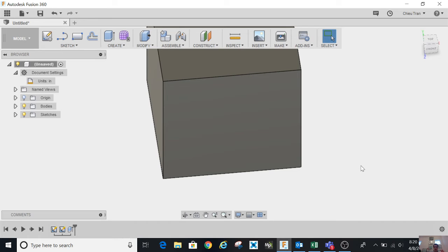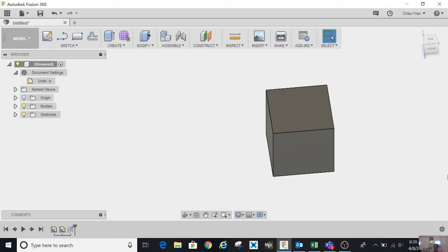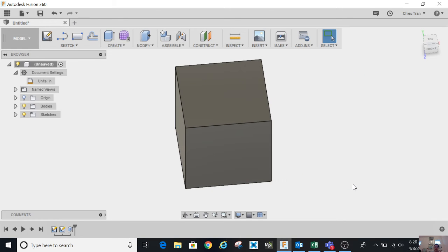One way to shrink the drawing, or make the drawing smaller, is this: if you have a mouse that has a roller, you roll down. Oh, it's the opposite, roll up. So that makes it smaller. Also, if you don't have that option, you can go down to the bottom middle. There is a window zoom. Click on that. Window. Click on that, and you draw a window, and it's going to zoom in.